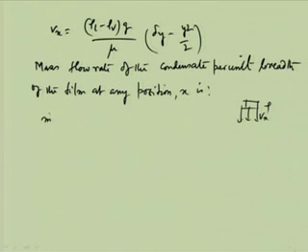So, we will find out m dot. This is nothing but the integral from 0 to delta, that is the range, 0 here and delta here, of rho L into Vx into dy into 1. So, this is the dy, and 1 is the unit width, and Vx is the velocity.